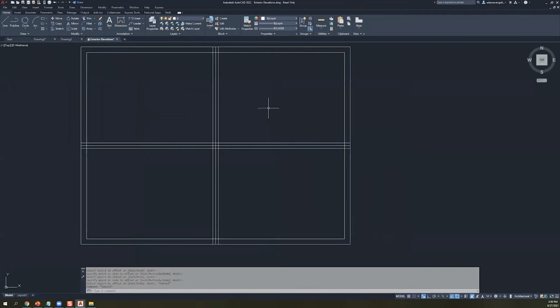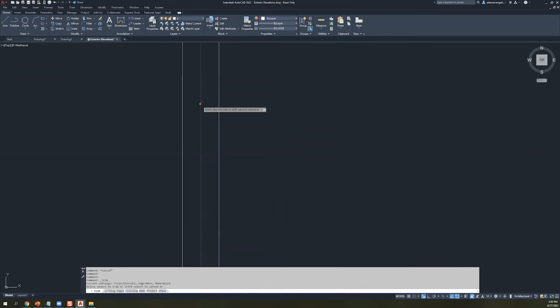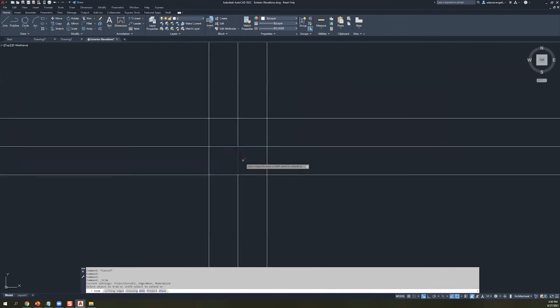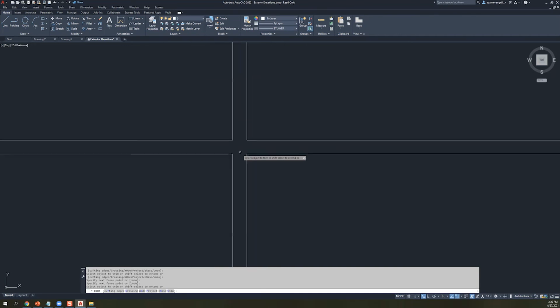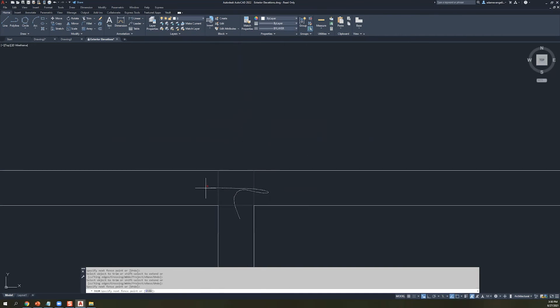And so the other big tool to modify geometry is the trim command in particular. The trim command did get some updates. I don't recall if it was 21 or 22 specifically, but now the trim command acts more similarly to how it does in Inventor, where you simply mouse over the parts that you want to delete, and it'll pick up the 2 cutting edges around it and just take it out from there, right? In the past, what you had to do was select your cutting edges first. So for this line, for example, I would have to choose top and bottom, and then I would have sliced out this piece over here. But now it's just a single click, and there is a way to go back to the old method if you really want it, but I genuinely just don't recommend it.